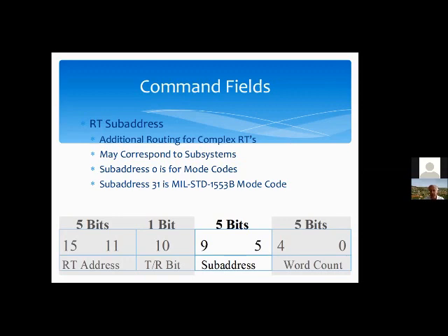And each one of them has its own data to send, and therefore it'll get its own message. And the way we distinguish between a message from the phased array radar and a message to whatever other kind of radar it is, is by using a different subaddress. Since there are 5 bits here, we have the potential for 32 different subaddresses. Now, 2 of those subaddresses are special, 0 and 31. Some planes will use 0, and some planes will use 31, and some might say either. If you use that subaddress, we're talking about a mode code, not a standard message.